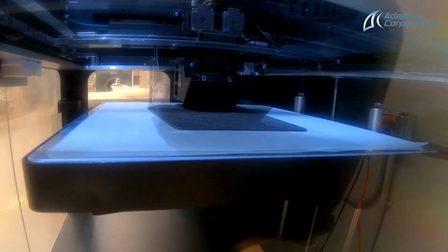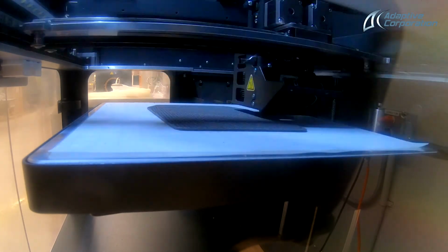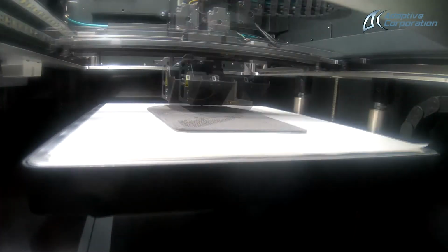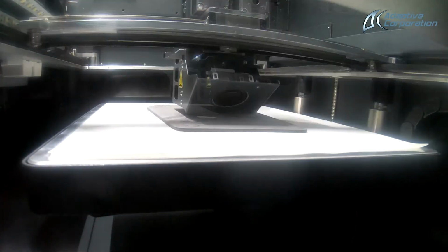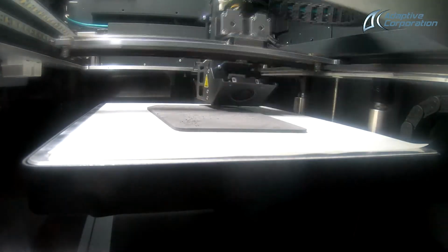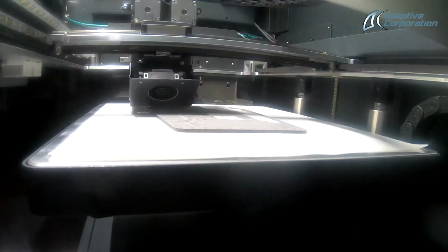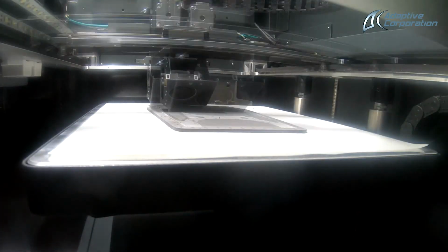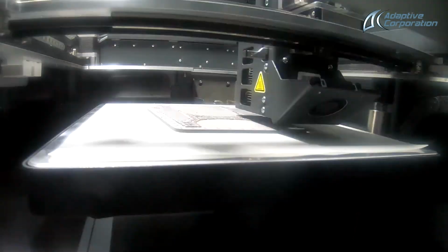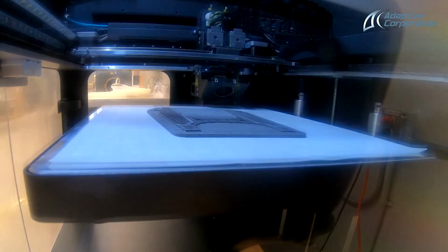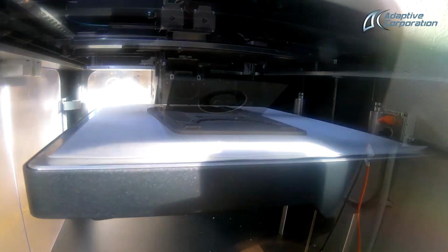Now that we have selected print, let's touch base on what happens next. Before the print starts, the Metal X maps and levels the bed to ensure the first layer goes down well. The print is done with two materials: the material selected for the part, which is made up of a two-part plastic binder and the metal material, and the ceramic release material, which is extruded as an interface between the part and supports. This is done layer by layer as needed, making these structures easy to remove after being sintered.